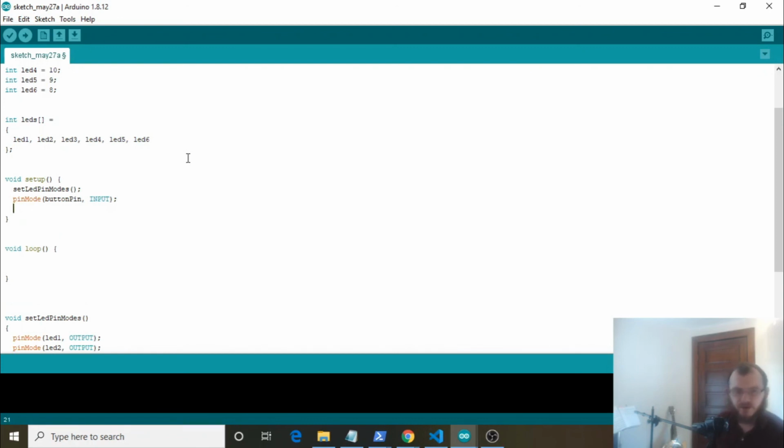So underneath there, we need one more thing, because we're going to need to create a random number during this to specify a random number between 1 and 6 for the dice roll. So we need to first create a random seed from some noise from the outside here from our Arduino. It's going to create a random number based on some white noise it takes in through one of its pins. So to do that, we can say randomSeed analogRead, and we're going to read from 0.